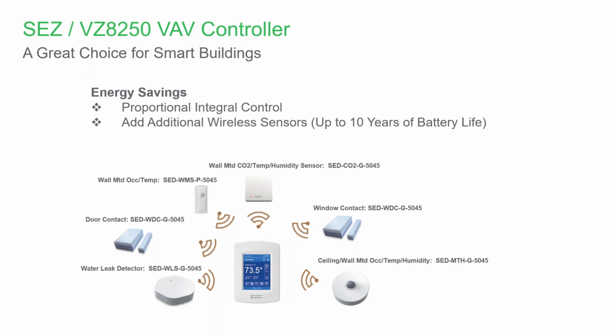What's important to understand too is each one of these devices feeds into an energy conservation measure or functionality within the room controller itself. I'm not going to peel the onion back too far on that, but for example, on the front of the room controller, you'll notice there are two little slots at the bottom of it. That's a light level sensor and a PIR detector.